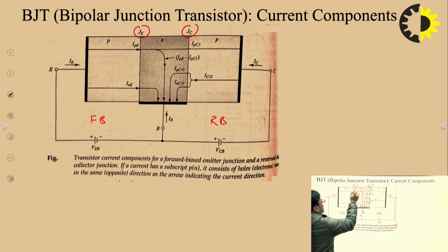That's why we represent it by P, and this is IE, right? This is the emitter current due to the electron, because the electron is the minority carrier here. Because this transistor is connected in the active region, holes are transferred from P to N and again N to P. Suppose I take 100 holes being transferred from the emitter to the base.